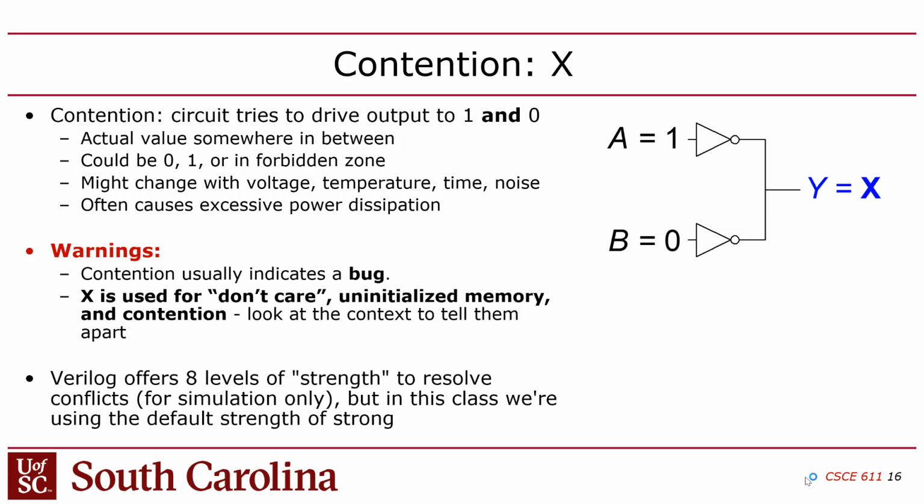Now, Verilog has this thing, and I've never really taken advantage of this, but it has this idea of drive strength. So when you simulate your design and you set a value to 1, you might see ST1 listed, which means strong 1. So there's this idea of a strong 1, a strong 0, and a weak 1, and a weak 0.